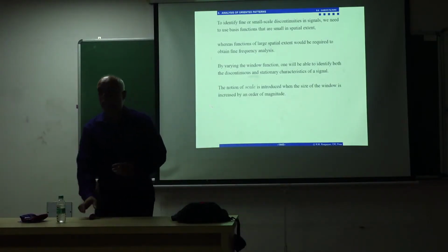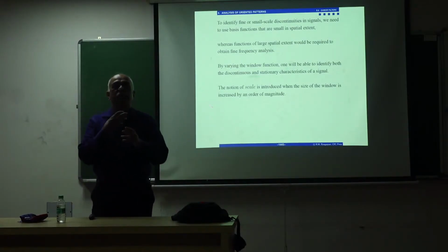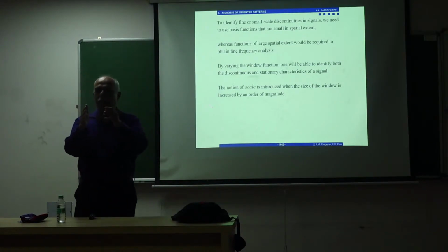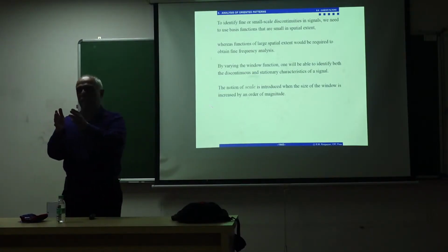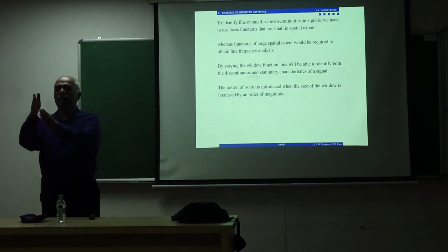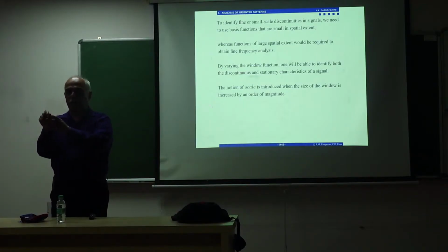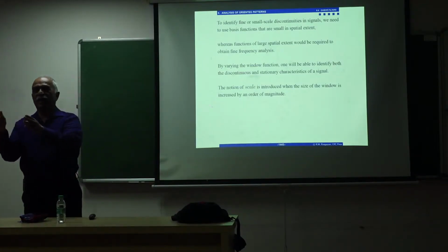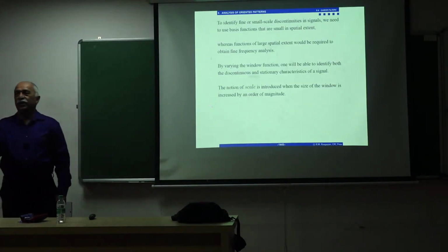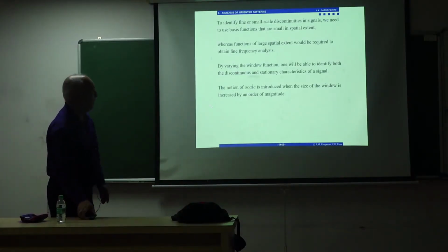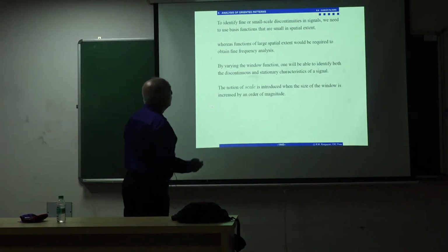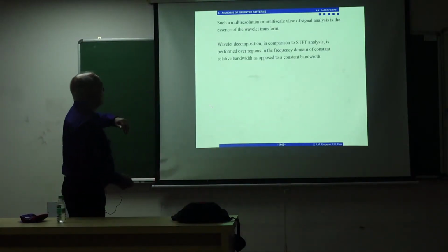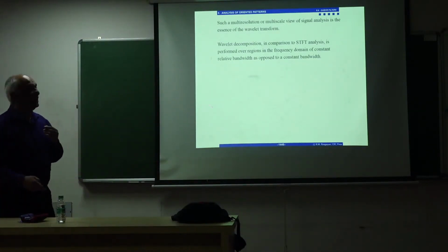So in speech signal analysis, as long as the same speech segment is produced, the same phoneme, as it is called, like ah, you have the same window, keep growing the window, and when it changes, like ask, and is comes, then you say, I'll stop the window, start a new window. And then T is a plosive, so it'll be a small window when it starts and stops, and so on. So adjust the window size depending on what is present in the image or signal. So you can call that multi-resolution or multi-scale analysis of the signal.